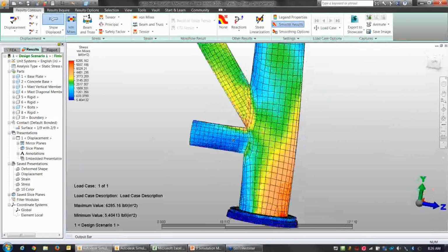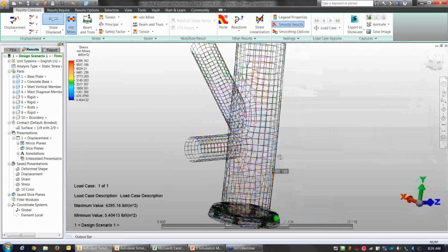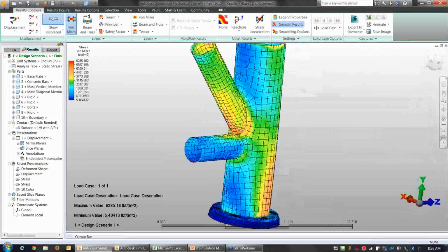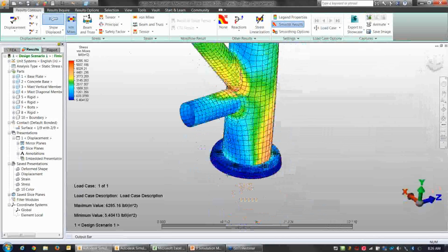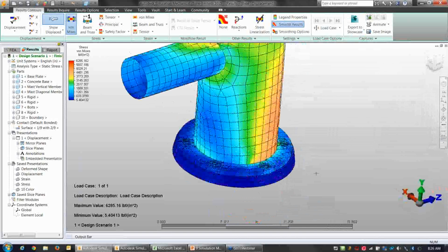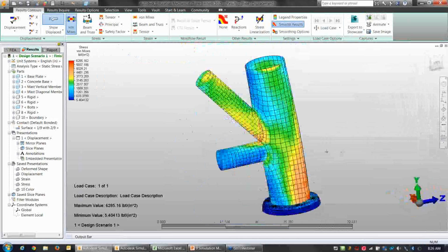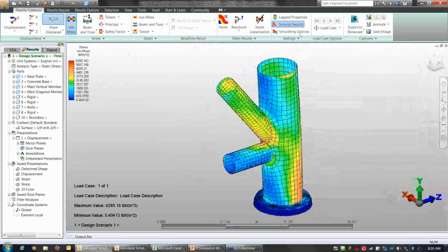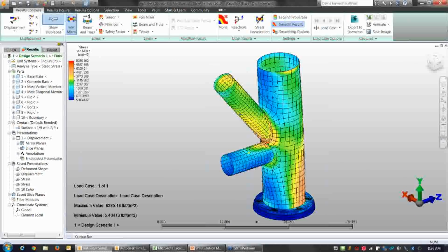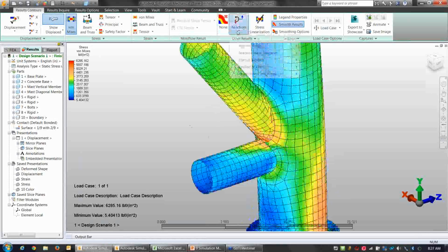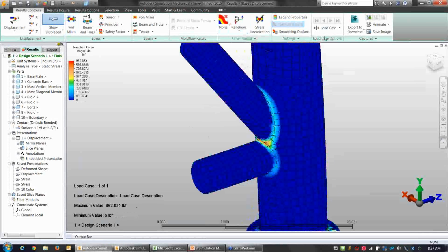And another thing to look at. Our stress is there. Okay, good. So our design criteria, at least with the plate here, we seem to meet it. We're not experiencing failure anywhere. That's really good. And the other design criteria, weld. We wanted to look at the weld strength between these diagonal cross members and the main mast. So we'll take a look at reaction forces.